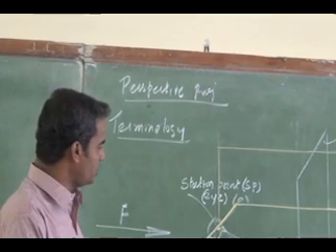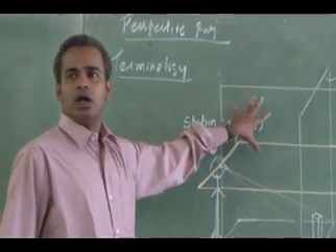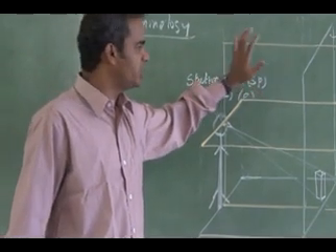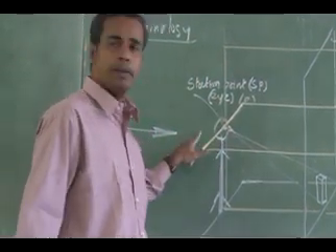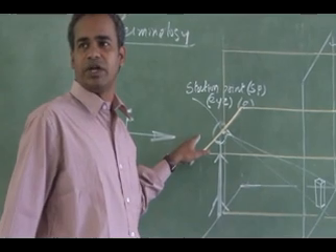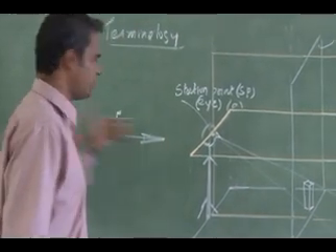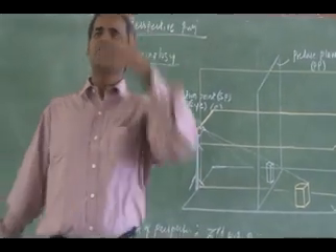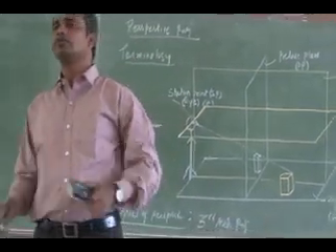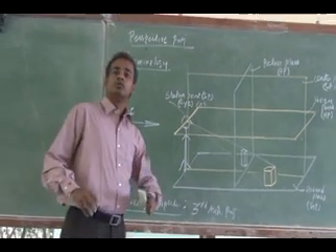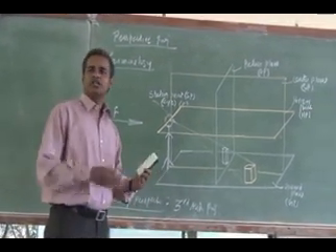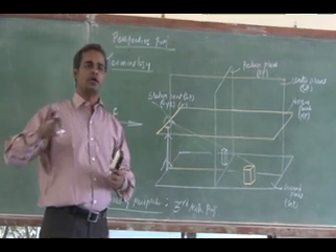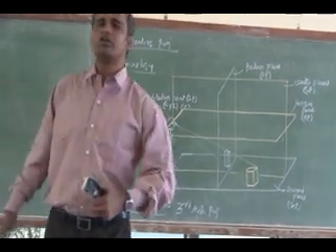So you try to tell me the layout for this whole setup. I have 6 components here: 4 planes, an object and a station point, right? So this is the front direction I am looking into. So what is the third angle projection? Where will I have the front view, where will I have the top view? As per third angle projection, any object's front view will be shown below the top view, right? The top view will be above the front view, right?